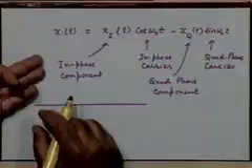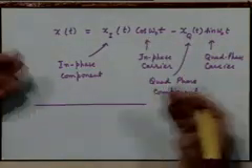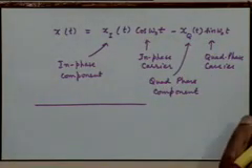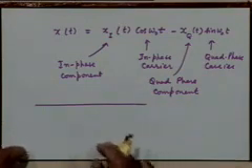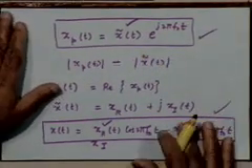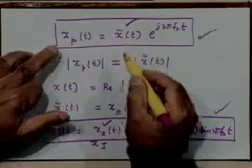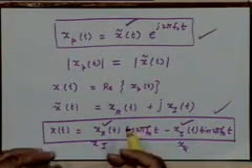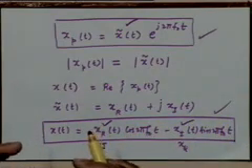So it is a very, very useful mathematical representation, keeping in mind that in this representation we have two low pass signals and a carrier. It really helps to define things very precisely. Equally useful is the other representation from which we derive this one. In fact, this is a more powerful representation than this in some sense. When we do analysis, it has the same power that the complex exponential has vis-a-vis real sinusoidal signals.